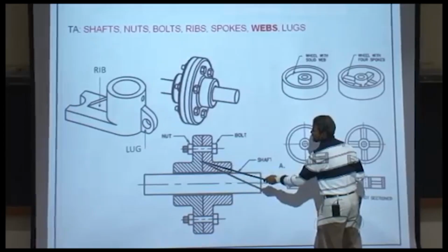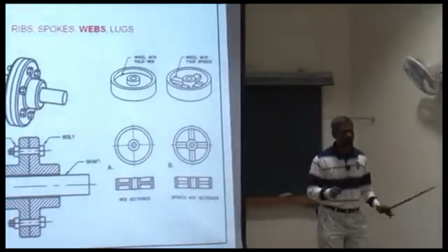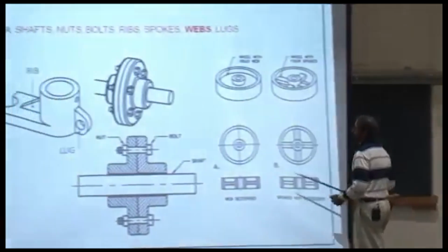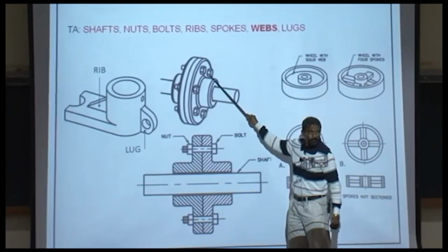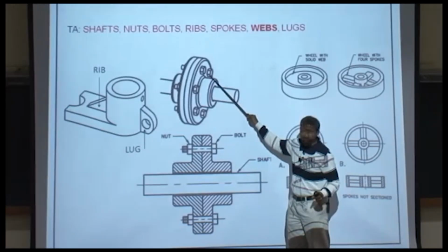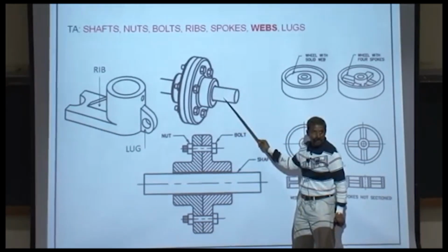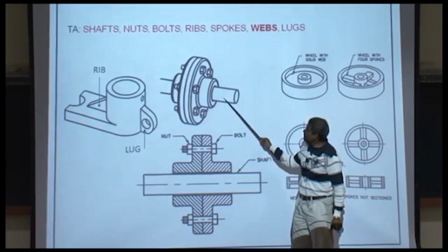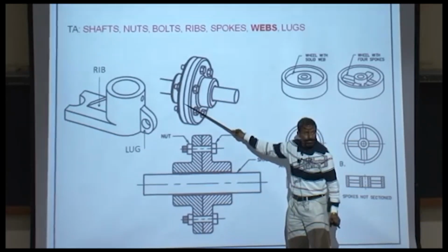Look at this example and look at the section view of this. Okay, so it's pretty much like, take the bolts out. Okay, listen to me very carefully. Take the bolts out. Take the shaft out. What you're going to be left with is this flange and this flange. Take the full section.